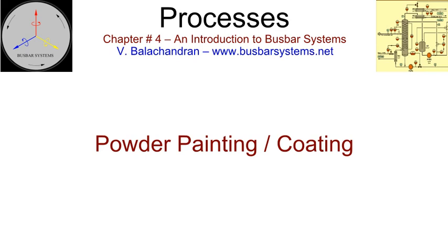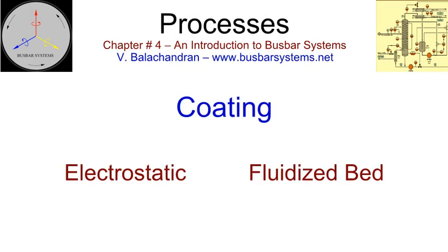The coating thickness of powder coating is limited. The thickness of the coat can be marginally increased by exposing the object for a larger period. It is not possible to powder coat an object that has already been painted or coated. Powder coating is done in a batch or continuous process depending upon the size and shape of the object. Large objects that cannot be accommodated in an oven or a booth need to be necessarily liquid painted, suitable for air drying.